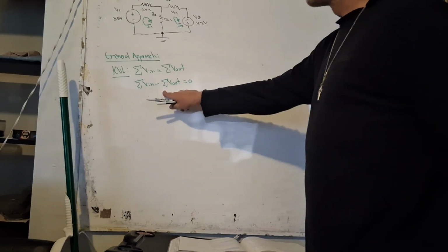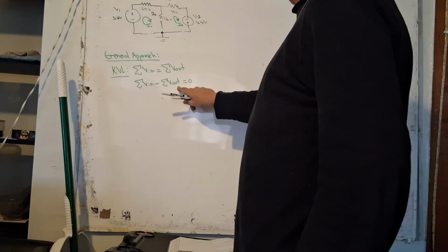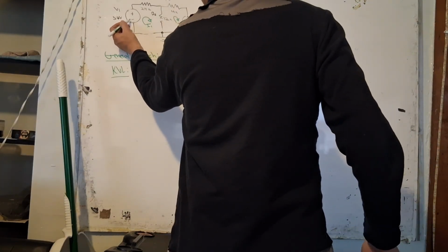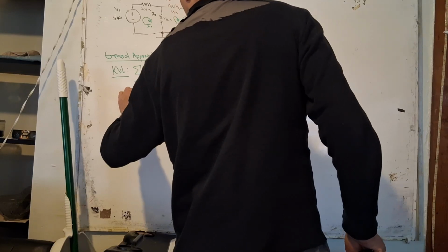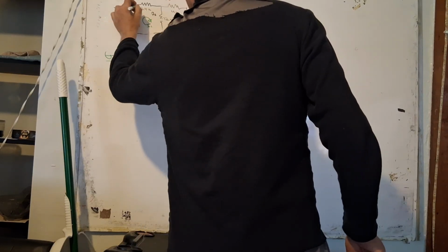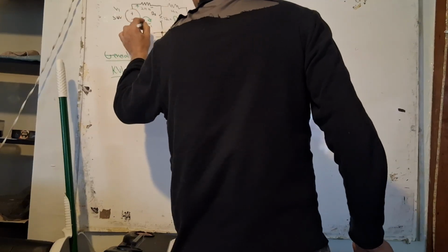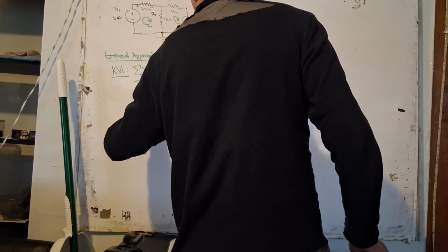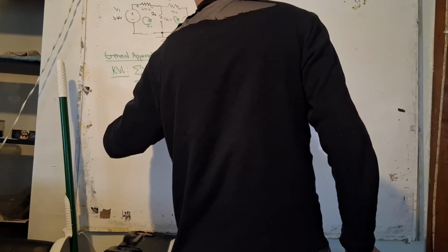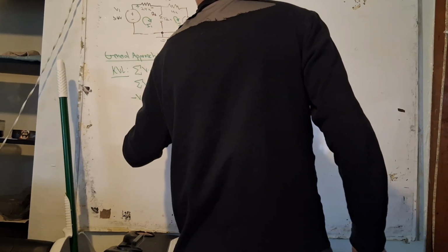And when we look at this expression, we want to say, okay, can we relate this equation to this loop? Yes, we can. We can start here and say negative V1 plus, going in this direction, I1 R1, plus, and it'd be easier to write it this way, R3 times the parentheses of I1 minus I2.